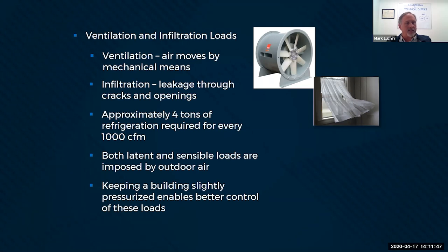If we keep the building slightly pressurized, that enables us to control these loads better because we can get a better handle on the infiltration. We can minimize the infiltration. One caveat with that is air and vapor barriers become pretty important.